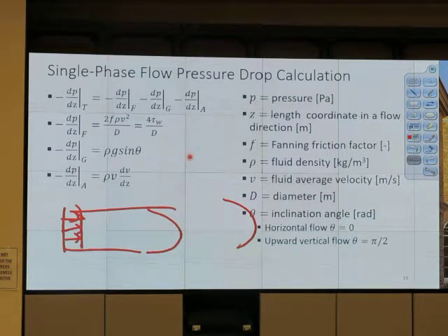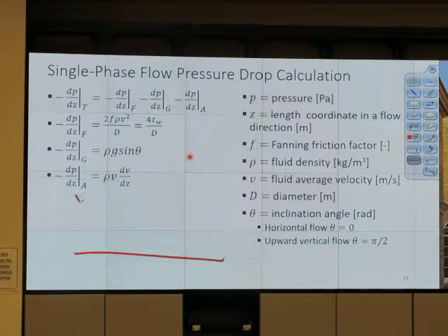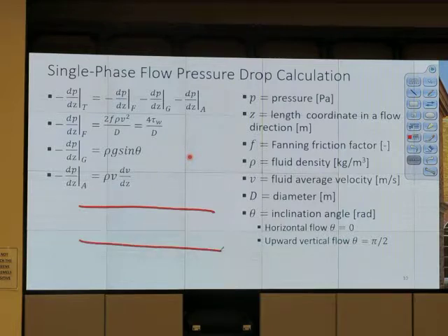All right. Can this equation be used for transient flow? No, not for transient flow. It is a special condition for transient flow, which is when t approaches infinity. Okay. If you wait long enough, pressure drop will be like this. Even though I say in the pipe, pressure drop per unit length looks like that, more near the inlet, and goes down and reaches a constant value. In the actual test, you may not find this because of the inlet condition. So if we have perfect inlet condition, near the inlet can have more pressure drop.